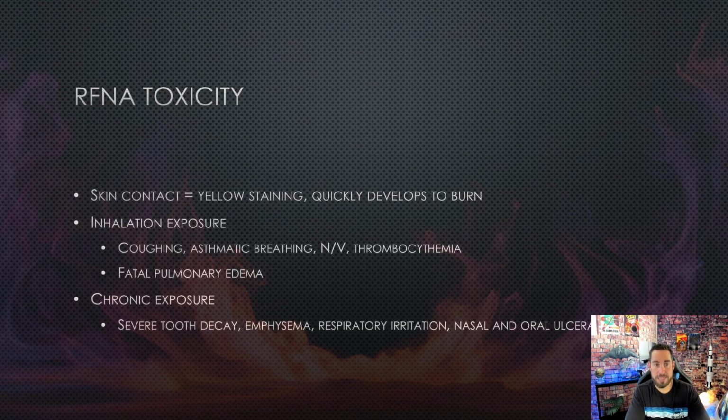It's fantastic from a hypergolic perspective. If you come in contact with it, it'll immediately stain your skin yellow, and it'll stay like that for quite a while until the skin replaces itself. It quickly develops to a burn, so if you found yourself in contact with RFNA, wash it off as quickly as you can.